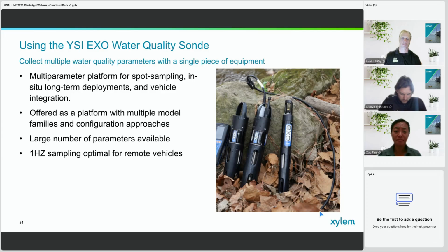And if you really want to get technical with it, you can also use GNSS heading if you're using an RS5 for your ship track, for your heading as well. So you can bypass any of the normal interferences that you'll see with either moving bed conditions or magnetic interference that way.